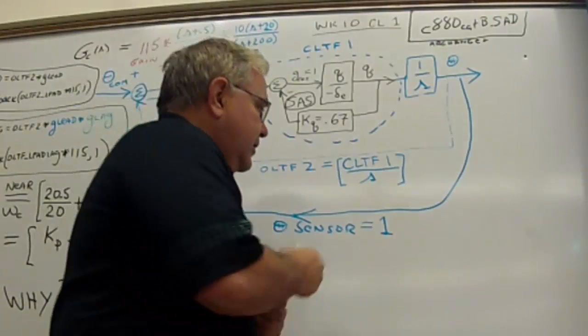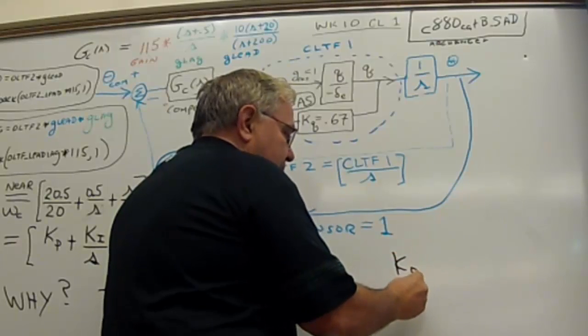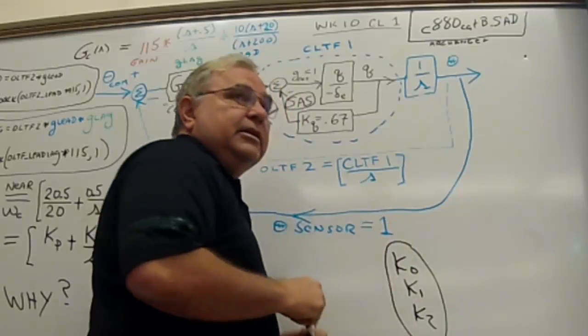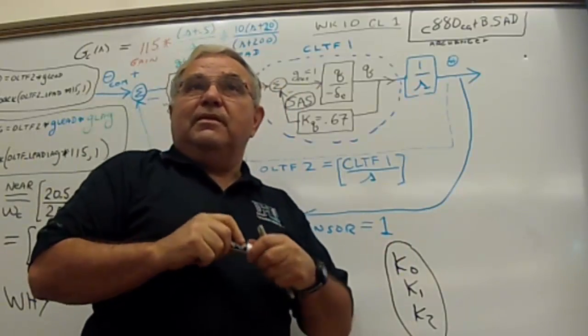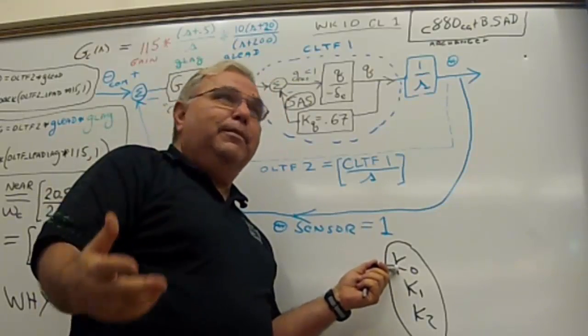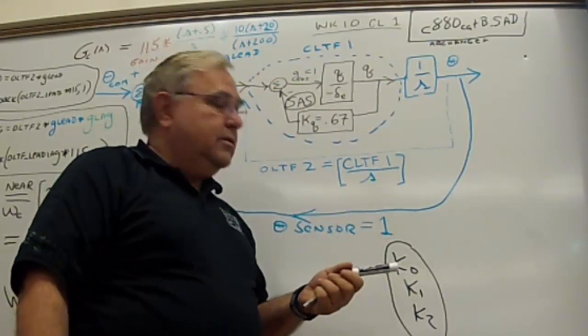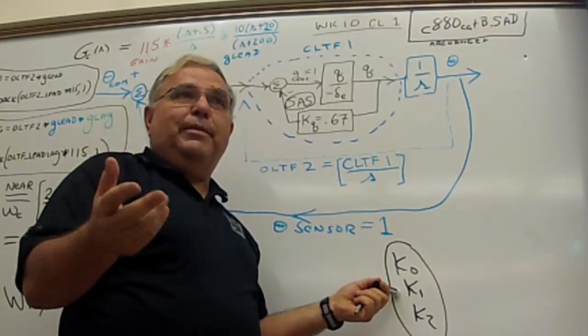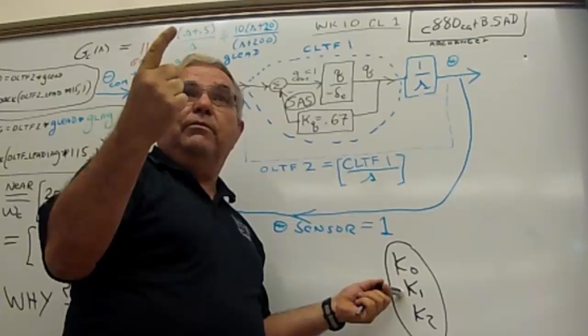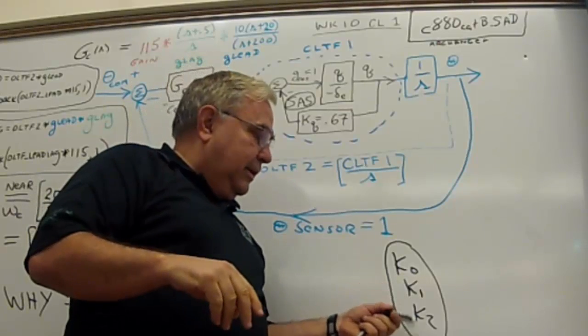We should talk somewhat about type gain for unity feedback systems on the outer loop. The outer loop is going to be a type 0 system because there's a 0 in the Q to minus delta E transfer function that will be canceled by the S that takes Q to theta. Therefore, there will be no integrals in the forward path. That makes it a type 0 system.